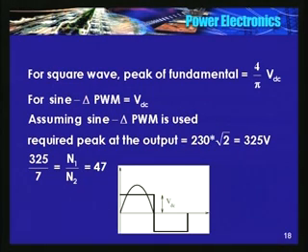And if you want a pulse width modulated inverter, because a square wave has higher frequency components, in the single phase case 3, 5, 7, all odd harmonics. In case you want a pure sinusoid, definitely you need to go for a PWM technique. And if I use the sine triangle PWM technique, what is the peak using a sine triangle PWM technique?